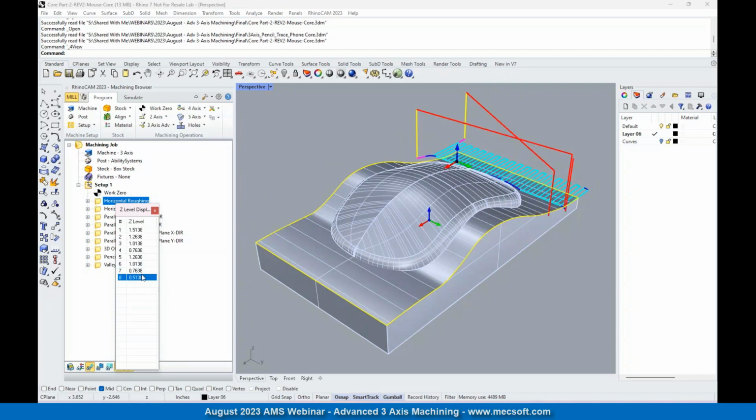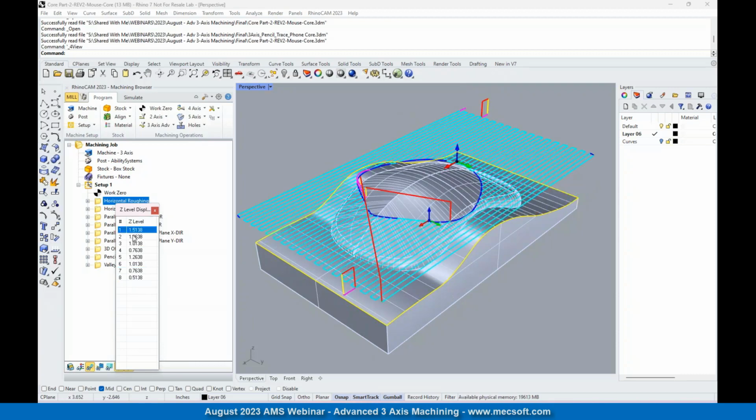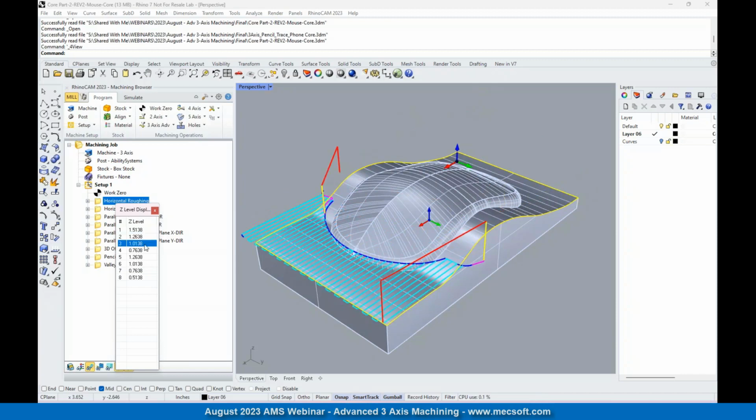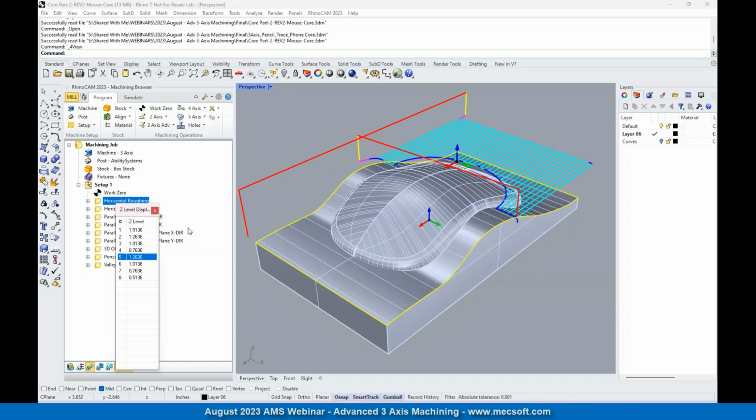As Don mentioned, other toolpath methods might help reduce the retracts and engages in a single area that you're machining. For instance, there you really don't have a retract in that area, but some cut methods might introduce retracts because of pinch offs. If that happens, using a different cut method might help reduce it. I hope that answers the question.